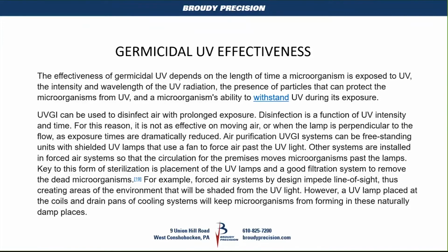And the key to this form of sterilization is the placement of the UV lamps, and good filtration systems to remove the dead microorganisms. That's our pleated filters or our bag filters or something like that. The reason UV technology has become so important, not only because of the biohazard, is that we can't be installing HEPA filters in all these air systems because of the pressure drop across the filter. We're just not going to be able to move as much air with all this filtration going on at the micron level.